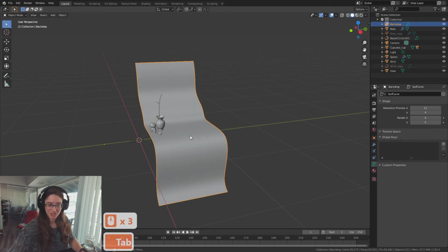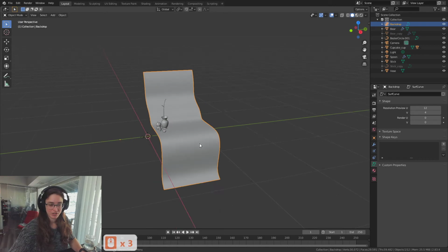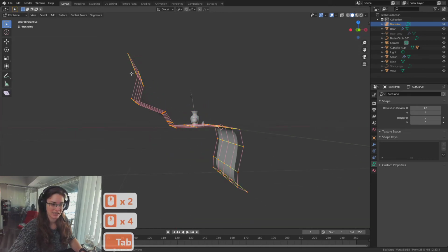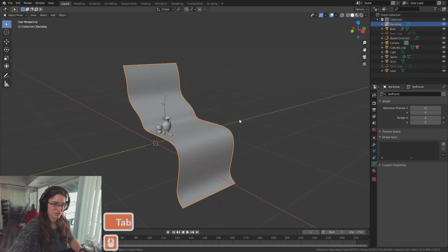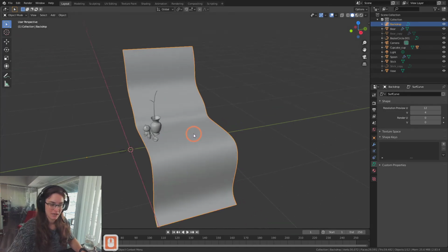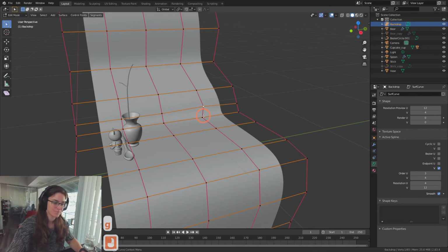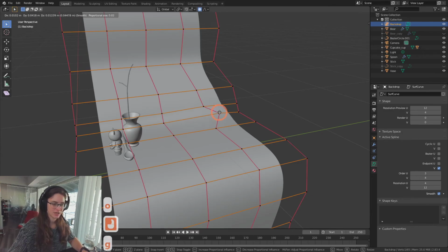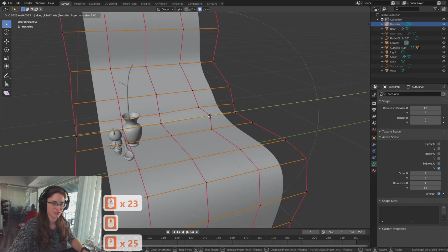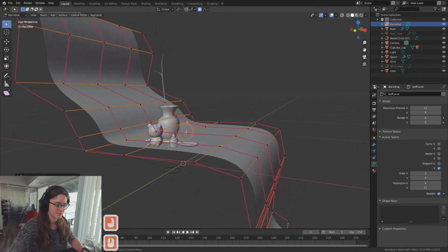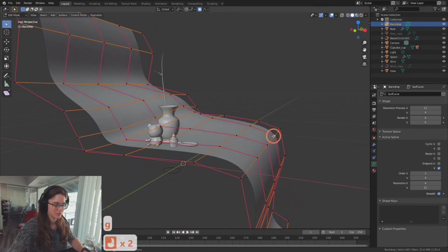And technically you could create this exact form with your NURB by drawing that squiggle and then just doing that default extrusion to make it branch out to the left and right. But the reason why we use the surface one is now I can go in and change the more, let me turn on soft selection. Oh, and increase my proportion. So again, O is soft selection, and then scrolling that wheel will change the influence.